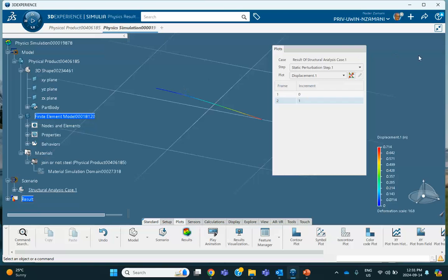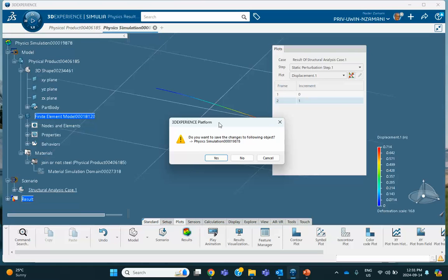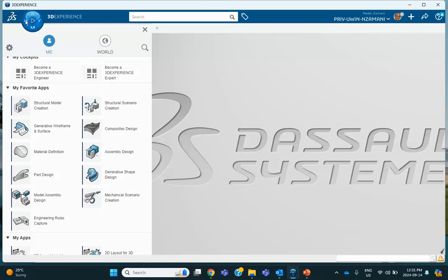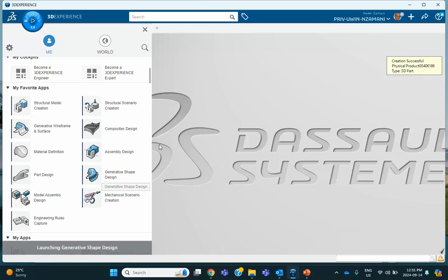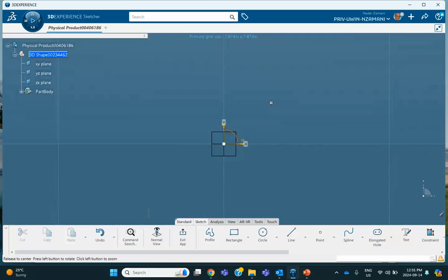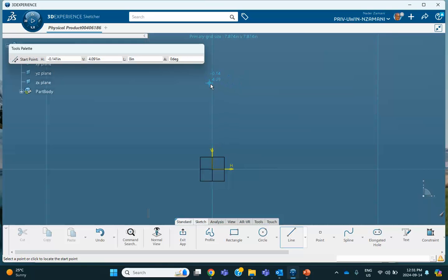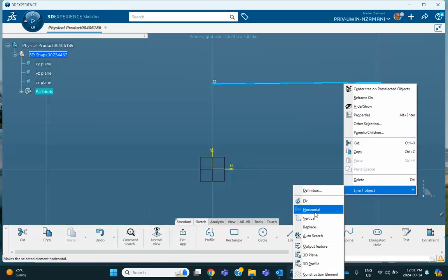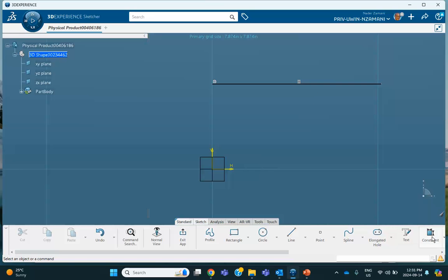Now, I'm going to get rid of this, start fresh. I don't have to set my units anymore, etc. And I will go to, notice that I don't need joining operations, so I can do it here or here, but that's okay. I'll go to the same place. Okay, so on that vertical plane, I will sketch a line up here, 120 inches. This vertical, horizontal. I like to make it horizontal. Good. The dimension has to be 120 inches.